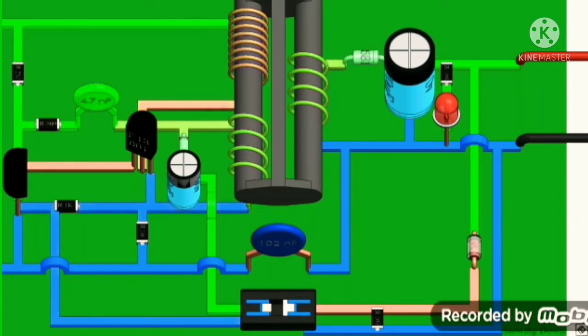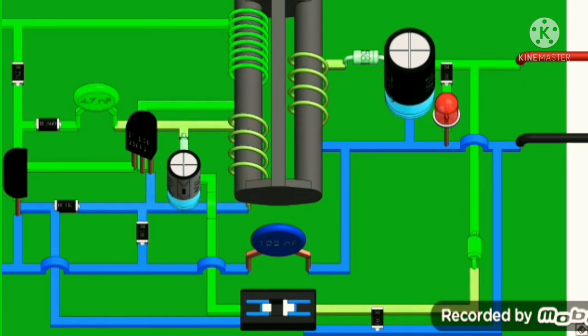Hence we have a feedback circuit. As we reach 4.2 volts, the Zener diode turns on, allowing current to flow to the optocoupler. It also drops the voltage by 4.2 volts, hence the LED of the optocoupler doesn't turn on. The LED requires 0.8 volt to turn on. When the voltage reaches more than 5 volts, this turns on the LED of the optocoupler.